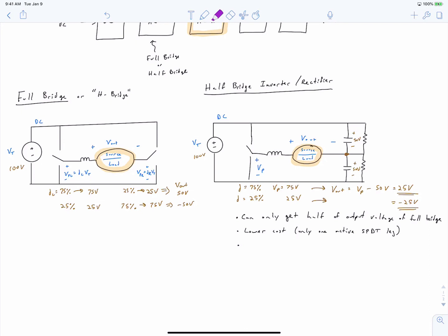So since V is equal to dφ/dt, the flux in the transformer is the integral of your voltage. This is Faraday's law. You need to make sure that your voltage has an average of 0 volts, or you'll end up causing your transformer to saturate.